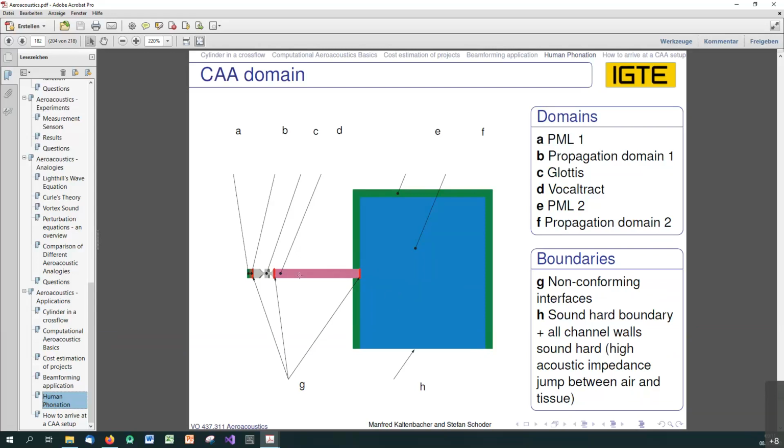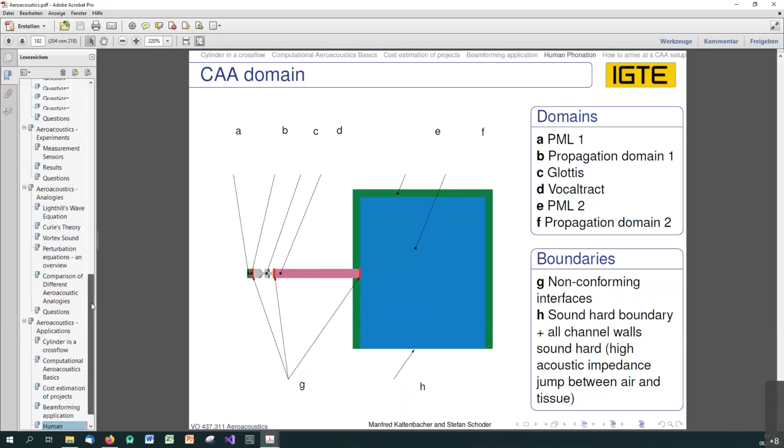The sound sources are produced and applied here on the wave equation, and then they are propagating out into the far field. This is all done with the acoustic propagation, all done with finite elements. And the flow simulation is done with Star-CCM+, a finite volume solver in 3D.